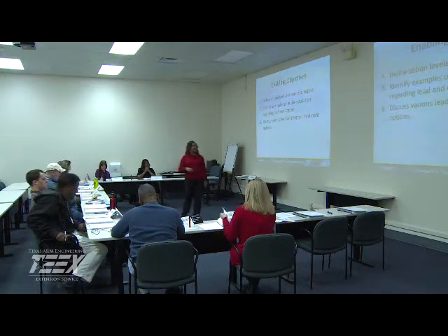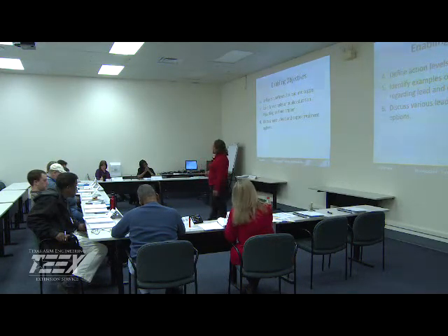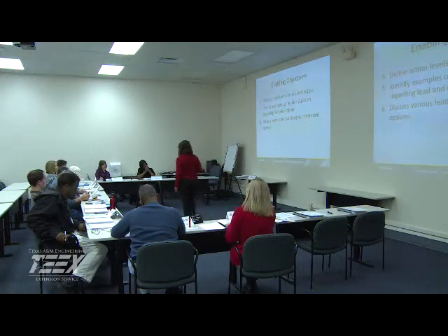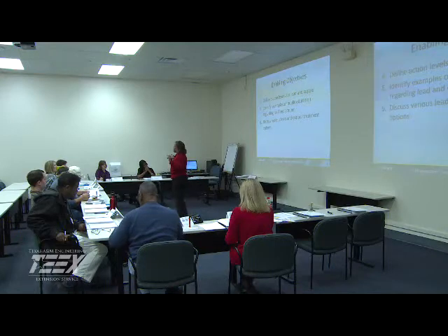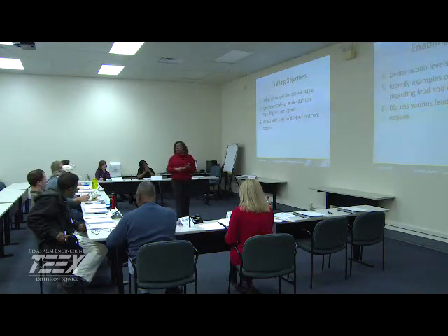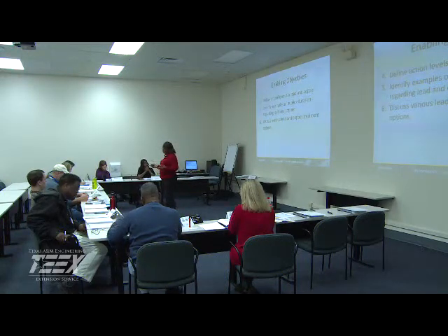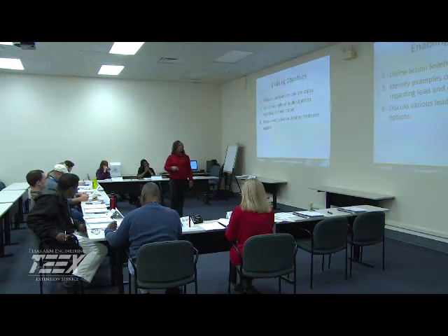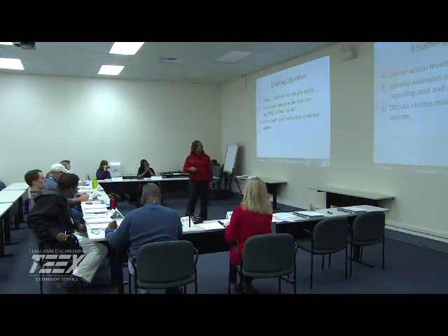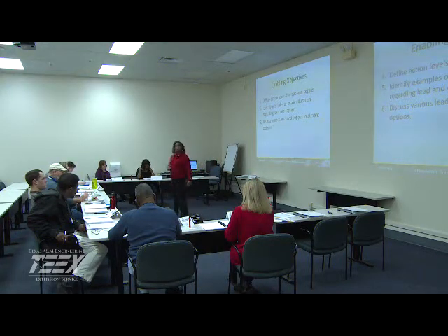We will identify examples of public education. In other words, if you exceed the action level or the maximum contaminant level, we want to make sure that we notify the public. Not only do we want to notify the public, but we want to give them additional tidbits. In some cases, it may be where to go to have your water checked, or you may want to seek a physician, or you may want to make sure you flush the water for so many minutes prior to using it first thing in the morning. So we want to make sure that we're passing that information along to the public, and then we will discuss various lead and copper treatment options that may be available.